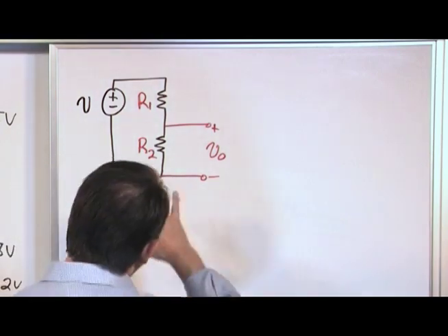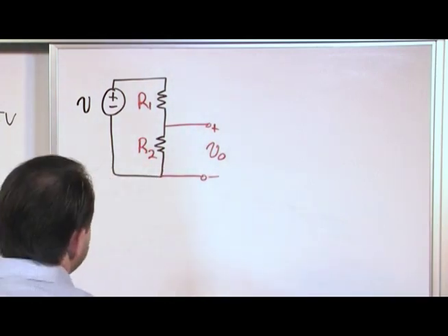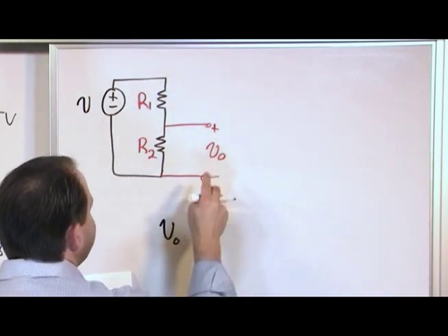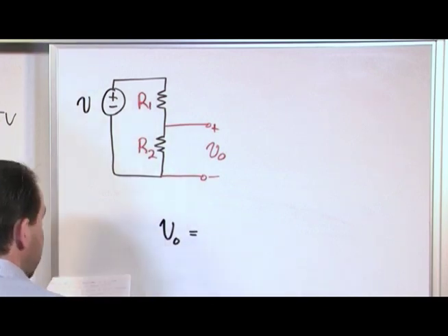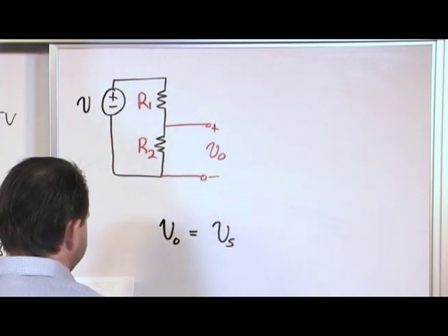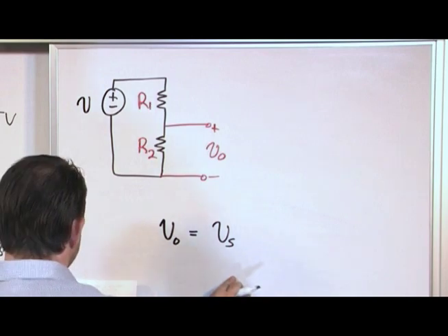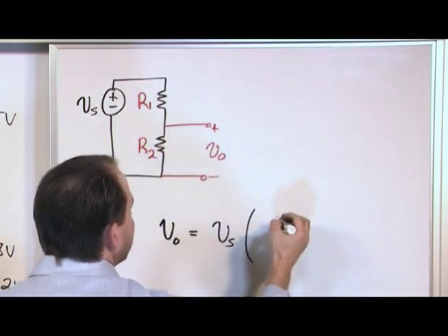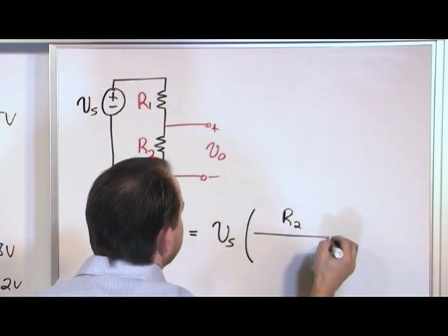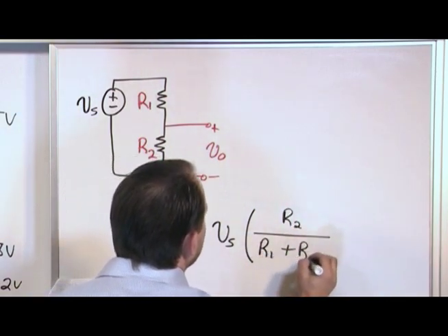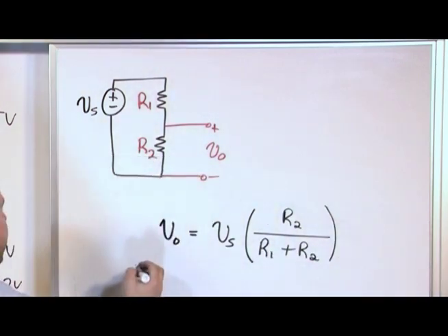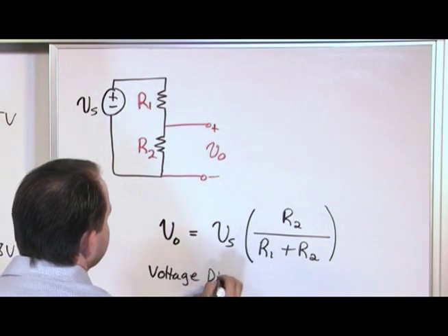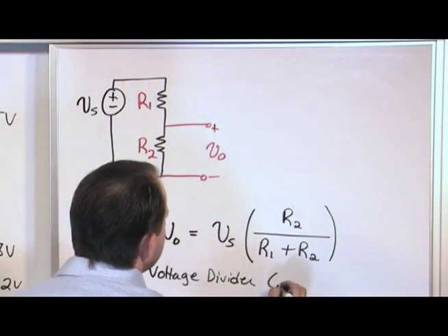The bottom line, when you use Ohm's law and figure it all out, and I've kind of alluded to that a little bit before, is the following. V naught, which is the output voltage you care about going to your load, is equal to the input voltage, right? Got to have something you start with, so I'll put Vs here, make it V source, times, since it's tapped off of R2, R2 divided by R1 plus R2. And this is a voltage divider. I'm going to put no load.